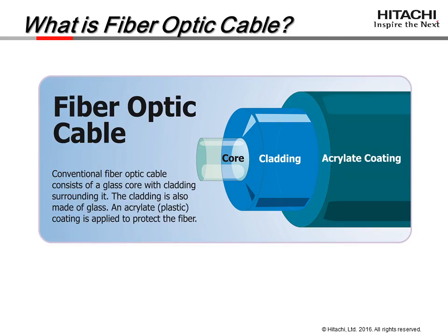The outside diameter of a fiber optic strand is generally about 250 microns. In this state, it is called loose tube. A human hair is about 100 microns. For added durability and to make terminations easier, an additional layer called a tight buffer is often added. This tight buffer layer increases the diameter of the strand to 900 microns.